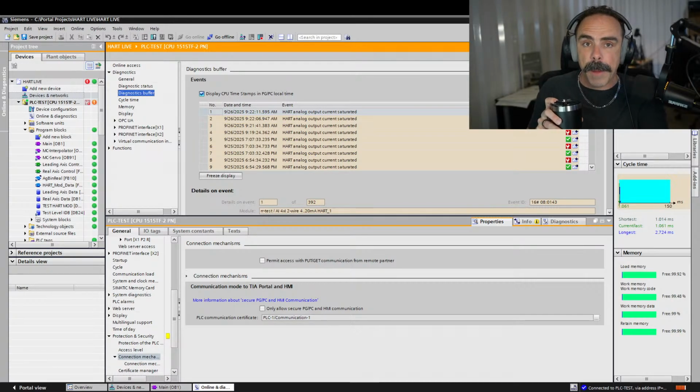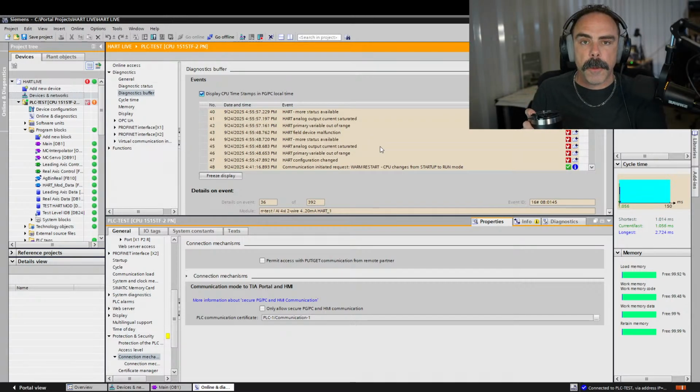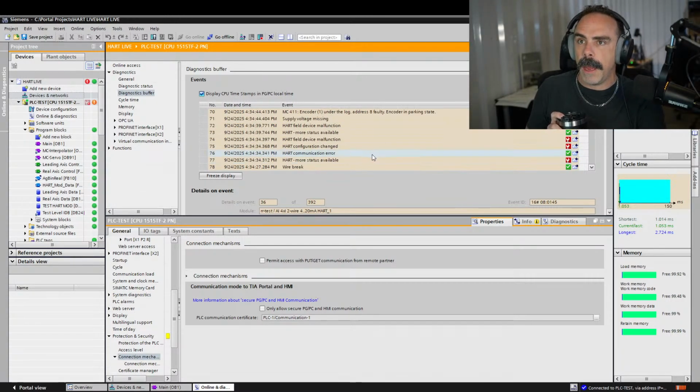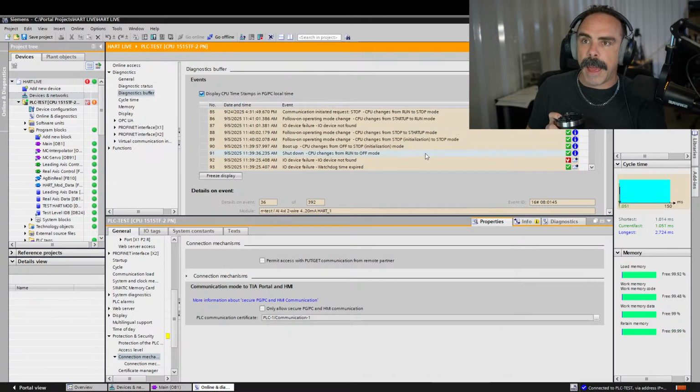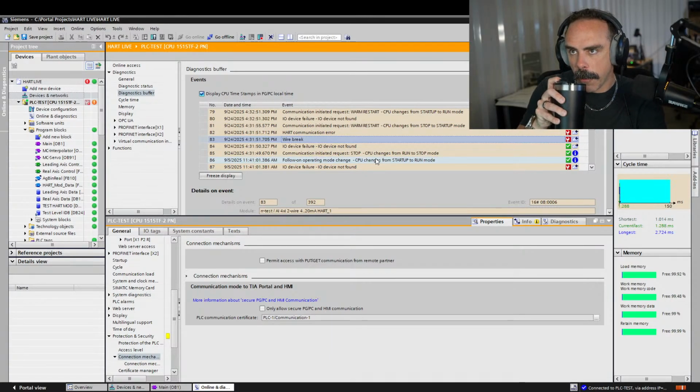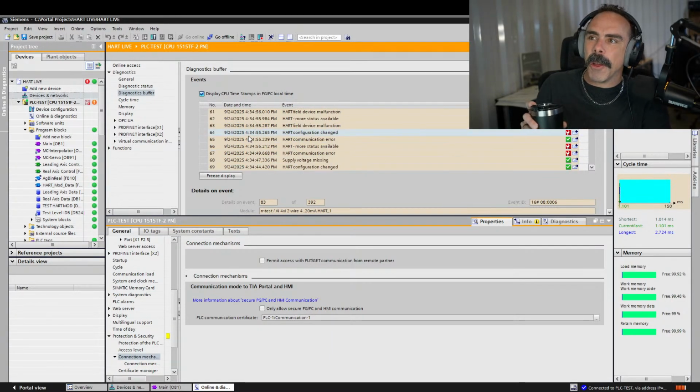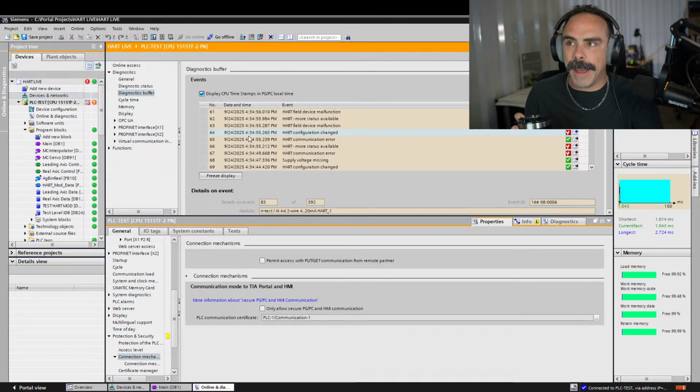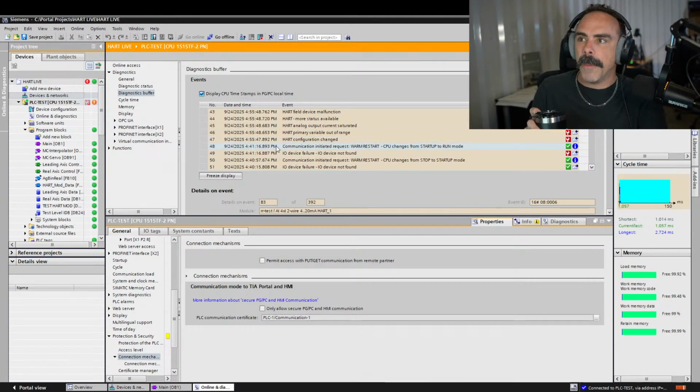And yes, you absolutely can bring these into your PLC. You can display these diagnostics on an HMI. These are the built-in diagnostics that are available to you in the 1500 processor. These are amazing. They tell you a lot about the system. Because I have this wire break, it seems like 924, that was me messing with it. So definitely set up your PLC time and date, because it can tell you all the stuff from me messing with it yesterday.